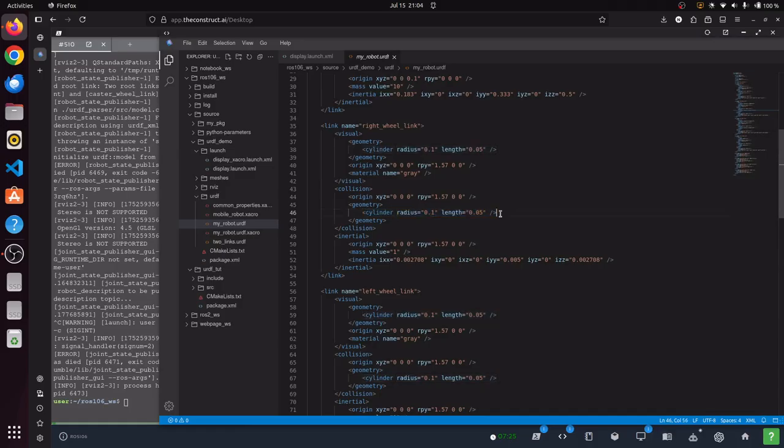So it only has one point of contact with the ground, and in terms of visuals it can stay the same, but when it comes to the simulation of friction and physical movement of the board, it helps a lot. I haven't changed that right now, because that might be a little confusing for others. So I've just kept it a cylinder, but that is one thing you might find in some URDFs if you open them.